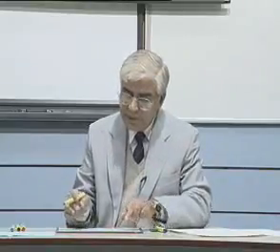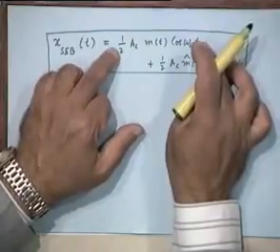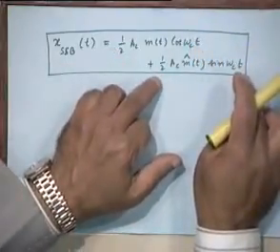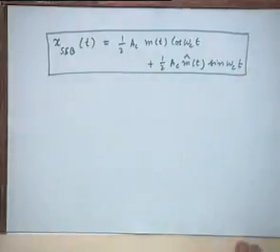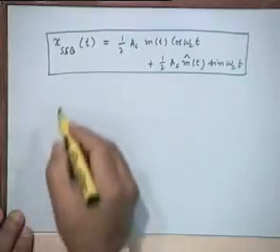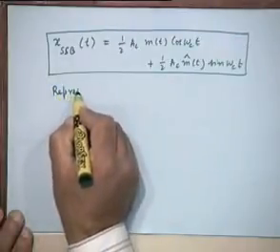It's not easy to visualize this waveform, because to visualize this waveform, you not only have to visualize this term, but also you have to visualize this. Now, for an arbitrary signal, one doesn't know what m hat t will look like. For certain kinds of signals, one can work it out. For example, for cosine omega mt, I can say that the Hilbert transform is sine omega mt, right? But for an arbitrary waveform, it is very difficult to see what the Hilbert transform will look like. So in general, it's very difficult to visualize it, but for specific kinds of waveforms, it may be easy to do so.